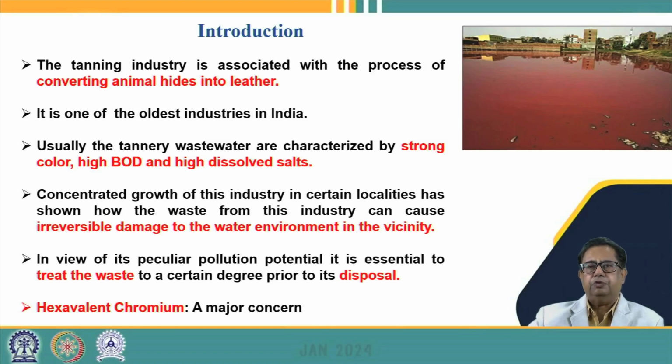The tannery wastewater that is produced because of this process, the conversion of the hides into the leather, may be characterized by a strong color. So we can have a very high color in it, not only because of the natural things which are present in the hides, but also because of the dyeing, or basically the coloring of the hides, because of which the color comes into the wastewater. Similarly, it may contain very high BOD values, because a lot of proteins, flesh, and organics are going into the wastewater.